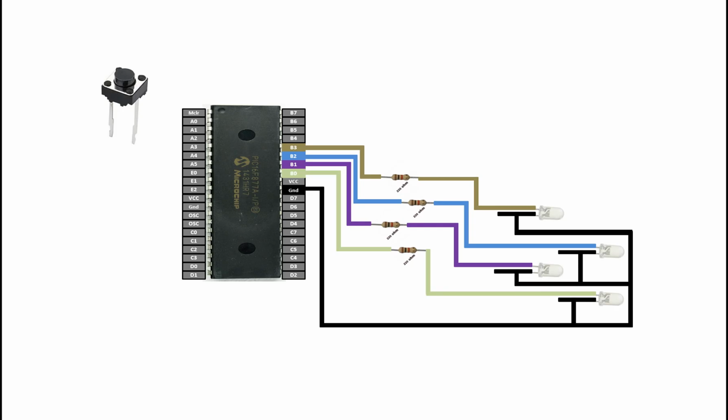This is the push button we are going to use, easily available in the market. It's a tick type push button. It has two pins, name one as the signal, other one as the VCC. You can shuffle these two pins as well. It doesn't matter because it's a non-polar component. Now for this button, you basically do not connect it directly, you will need a resistor. This is a 10 kilo ohm resistor I am going to use.